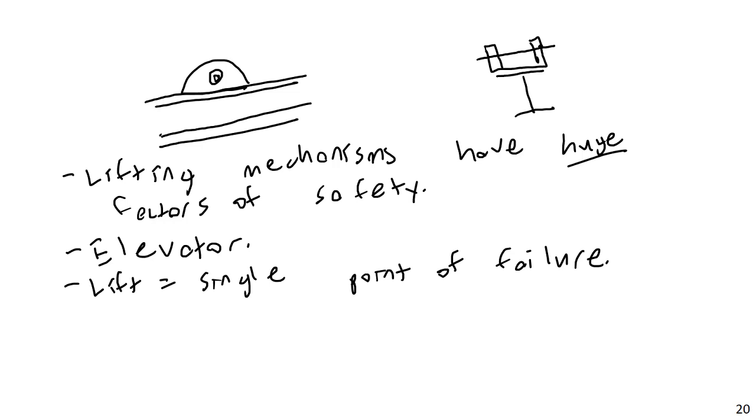But when you're lifting something, often you're supporting it by a single point, a single object, and so if that fails, the entire thing's coming down. Also, as it falls, it gains an enormous amount of kinetic energy, which means the damage can be much, much higher to anything underneath it, whether it be a part of another building, a person, God forbid, an automobile, whatever it may be. So lifts tend to have very large factors of safety purely because of the consequences of failure.